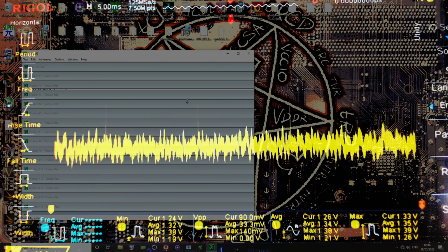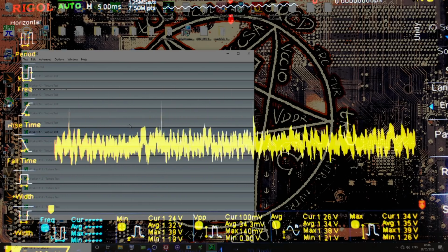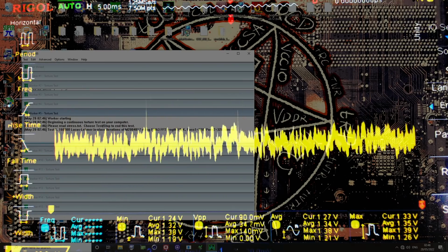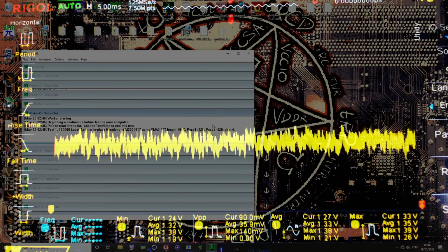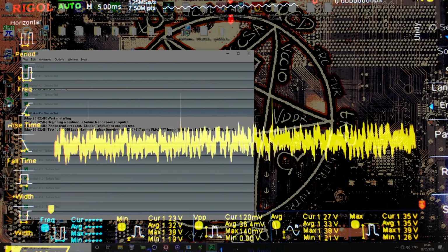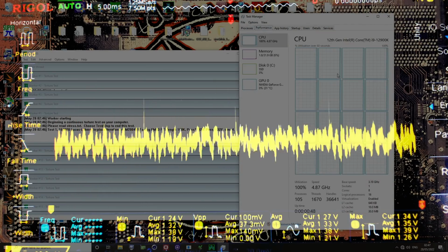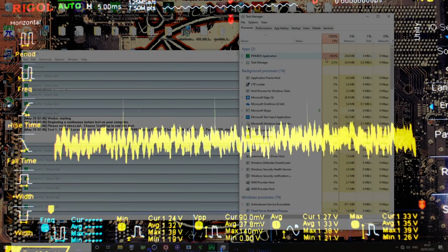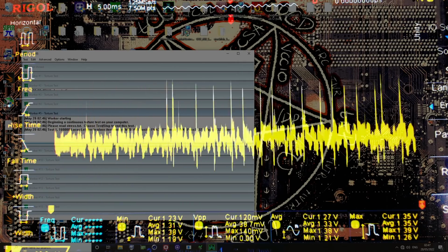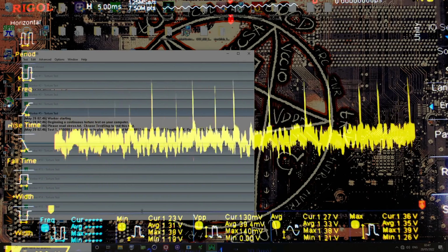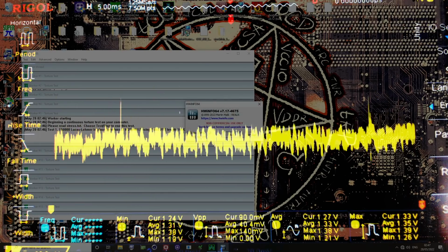So we are getting more voltage. I think the workload's different, maybe. What FFT size are we on? Oh, we're on 100K, so... Are we not loading all the threads properly? Wait. No, it says 99%. I move the mouse around. Okay, well now we have visible undershoot on the waveform when I move the mouse, so that's not great.